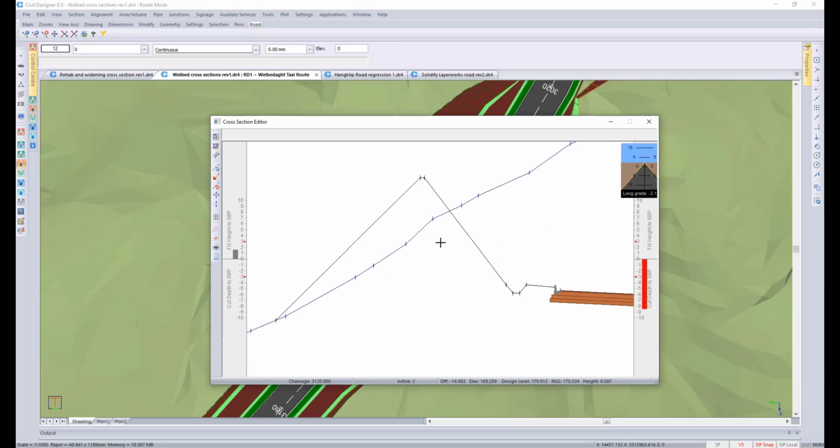The method that I wanted to show you over here as well is the functionality on a right click. So you've got this line intersection option over here. So I could just physically delete those points on that design layer, now the active layer. But then I wouldn't have an intersection point.